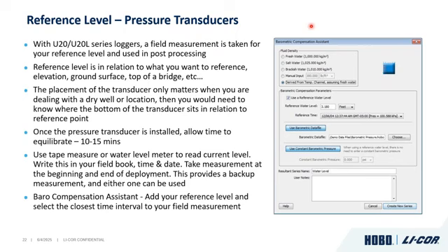So if you're in a groundwater well, it's a shallow one, your transducer is 2 feet below ground surface and it's dry. If you want ground to be 0, your starting point would be -2. And as that pressure transducer starts to see water, it will start from -2 and work its way towards 0. And you can use that style or that reference in any case.